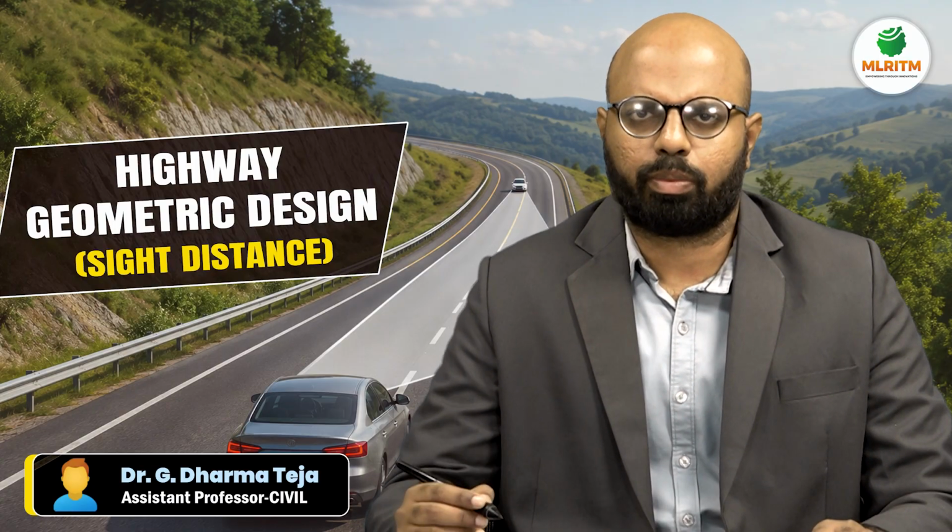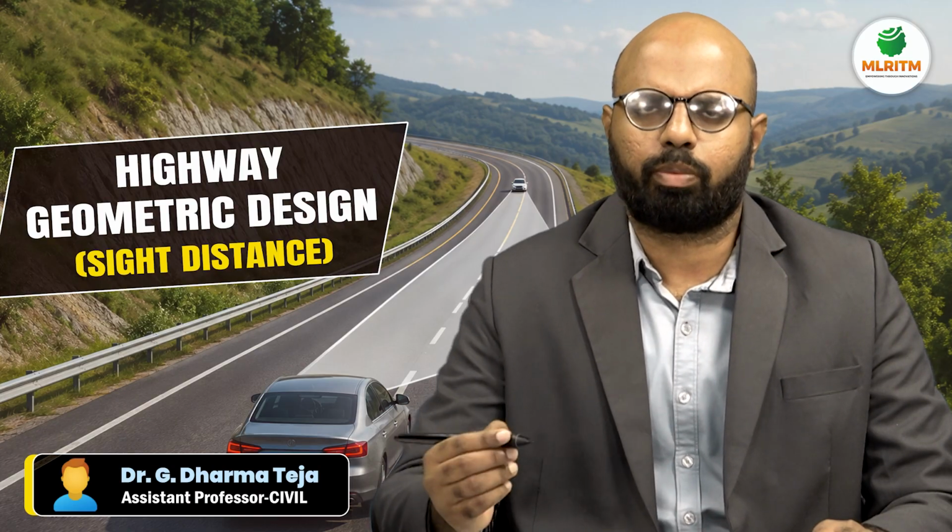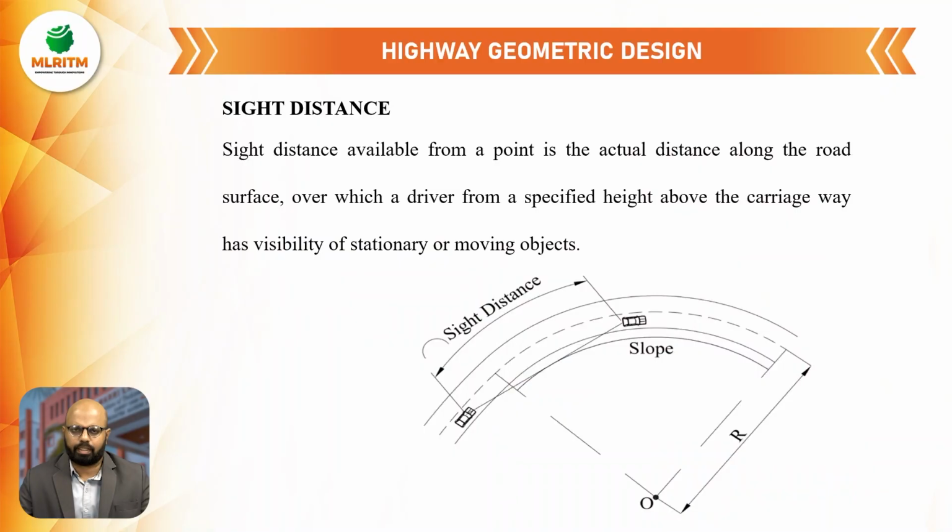Today we are going to discuss a topic, highway geometric design. In that, we are going to discuss a subtopic, sight distance. What do you mean by sight distance? Sight distance available from a point is the actual distance along the road surface over which a driver from a specific height above the carriageway has visibility of a stationary or moving object on the same lane.